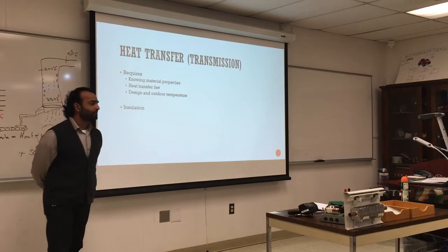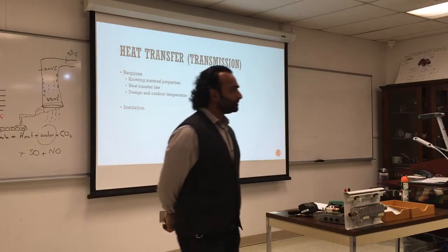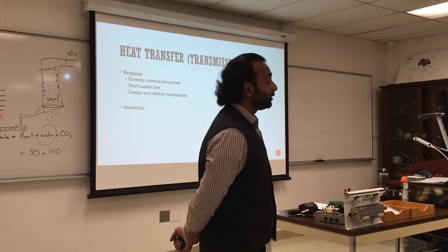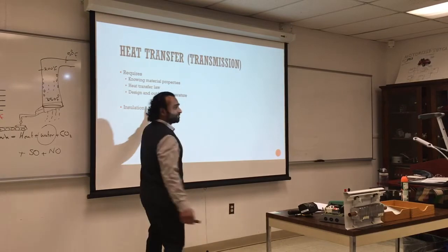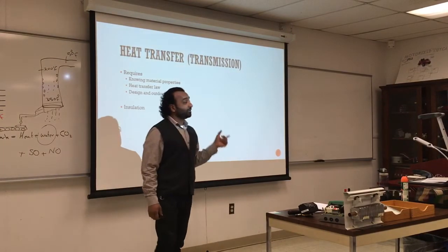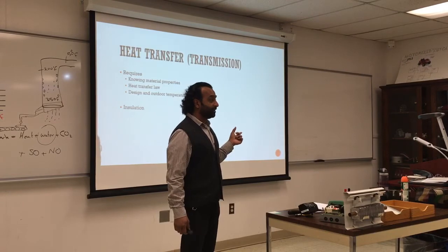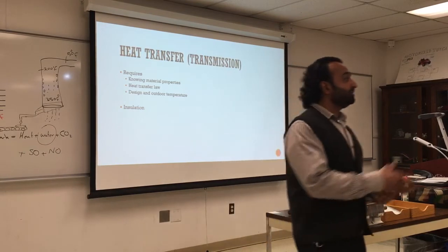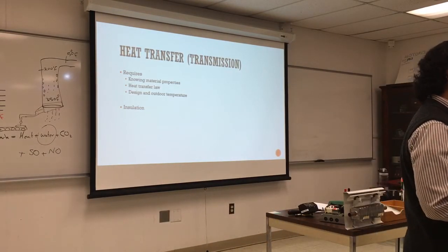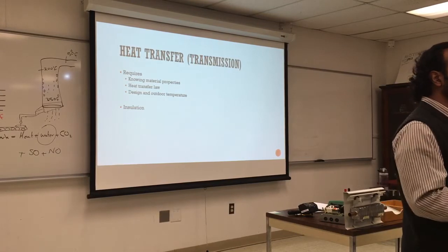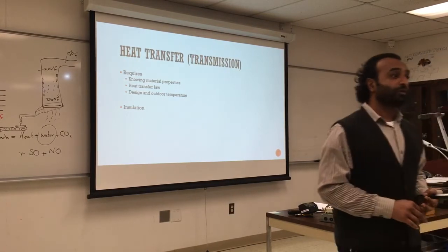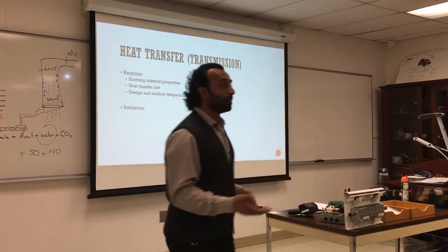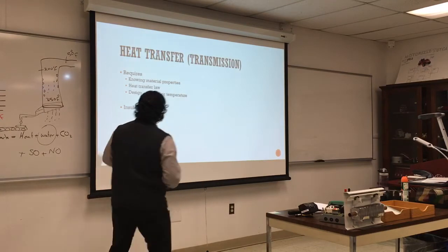When you're doing the outdoor temperature, is it the temperature at that time of day? Are you asking about the outdoor temperature? You're going to look for the coldest day of the year. You're not going to decide on 30 or 40. You're going to look up, for example, Chicopee, coldest day of the year. It's going to be 0. Maybe it's changed by now. This data has been consolidated over the last 10 years because they want to design for the most extreme possible case, where you will be able to heat the house comfortably and avoid the water freezing or the system breaking or whatever.